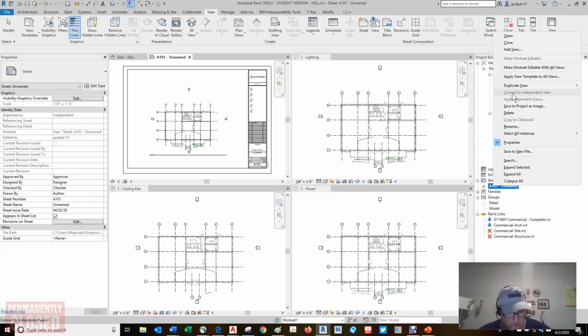Let's read back. If you want to get around this limitation, here's a helpful tip. Create a new sheet, but then delete the sheet border. This is now a workspace for any view of the project. Just be sure to label it as a working sheet apart from your documentation set. Now you can create duplicate views of any of your project views and assemble them in this working space. Zooming in and out is much more fluid.